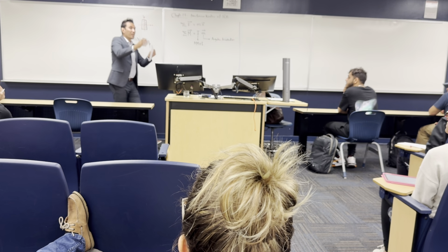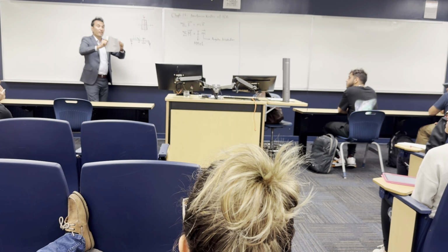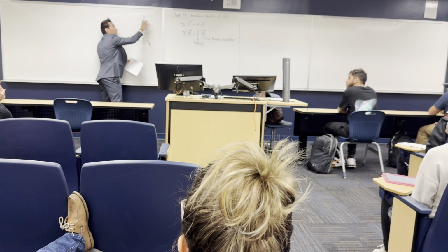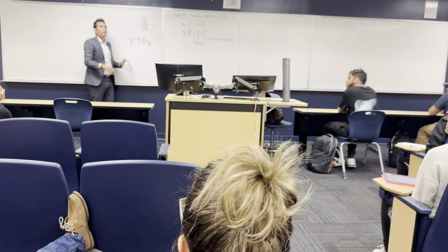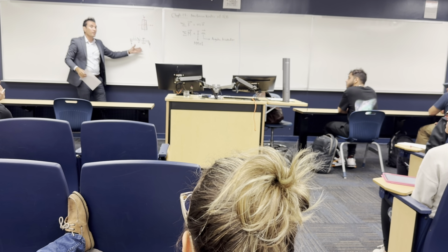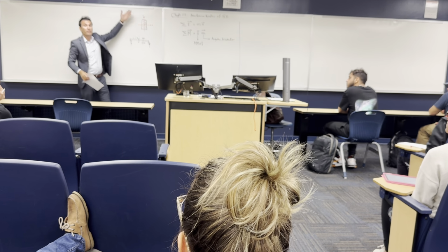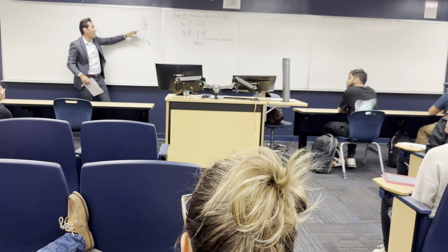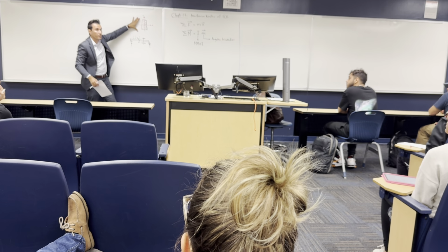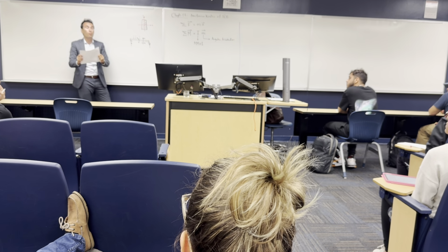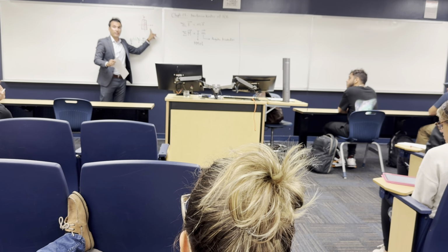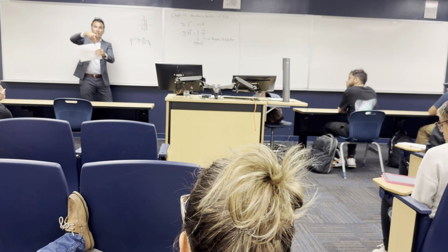If the load is coming here, this cross section is going to bend this way, about the x-axis, so that's what I want to increase. If you are designing this beam to carry this load and you find that this section is not enough and you need to increase the stiffness, increase the moment of inertia, I need to increase the depth because I need more inertia about the x-axis. Why? Because all the load is coming this way.